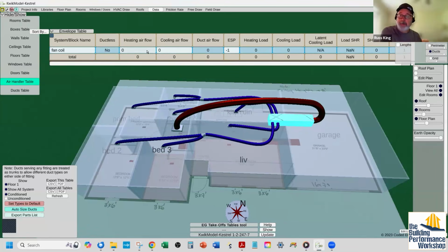This comes from the airflow tables for that particular fan coil unit. I'll just use some generic numbers. I'll just say 800. Heat pumps typically run on the same speed in heating and cooling mode. And FYI, everybody, if your Manual J says this many BTUs is your load, I'm going to imagine something that's running 1100 CFM. It's not a target you have to hit. That's just something that the software made up to deliver those BTUs.